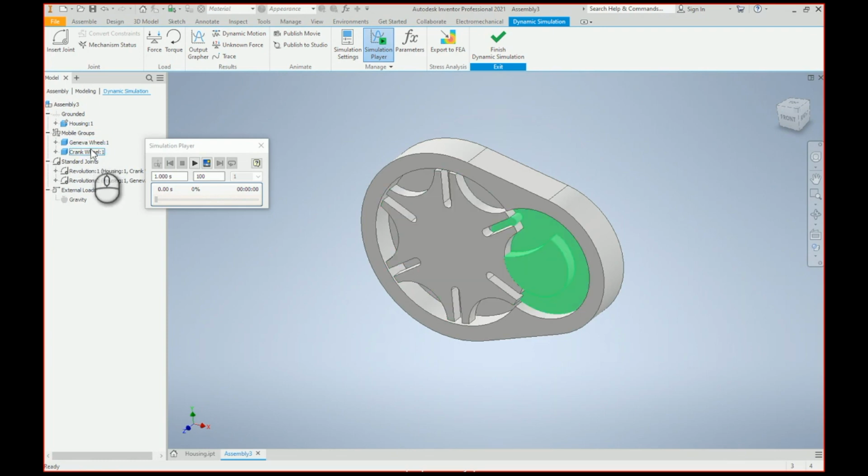The constraints we placed on the assembly left 1 degree of freedom for the Geneva and crank wheel, only rotation. On the simulation environment, it is translated to a revolution joint. We could have obtained the same by adding revolution joints between the wheels and the housing. A joint is a set of constraints.